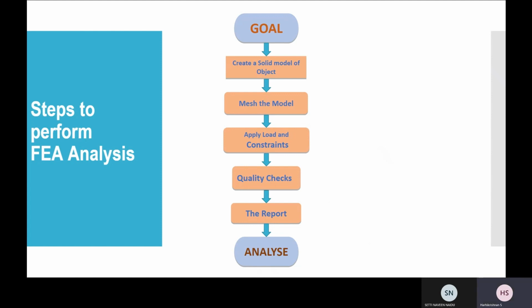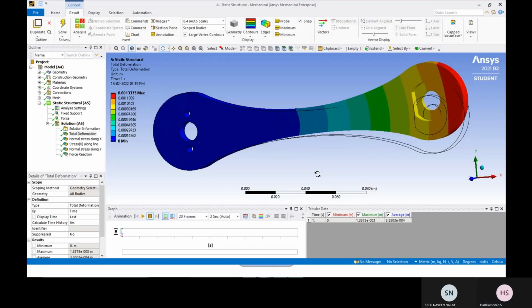And already I told you about meshing the model. The next step is applying loads and constraints to the model. In short, these are inputs from the user with a good understanding of how the system interacts with its surroundings. And finally, run the model, with the numerous quality checks required from the model, like error plots, reaction force, stress results, etc.